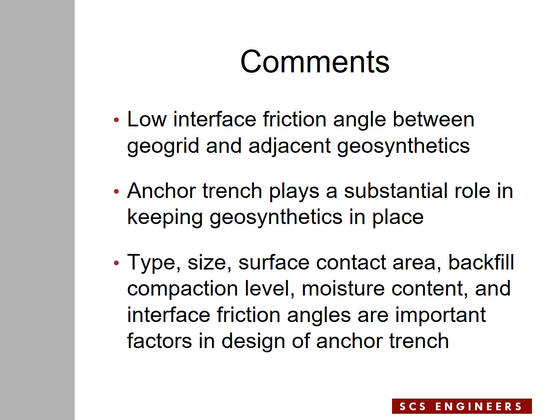Couple of comments. Low interface friction angle between geogrid and adjacent geosynthetics requires a significant anchoring at the top. The anchor trench plays a substantial role in keeping the geosynthetics in place. The type, the size, the surface contact area, backfill compaction level, moisture content, and interface friction angles are important factors in the design of the anchor trench.